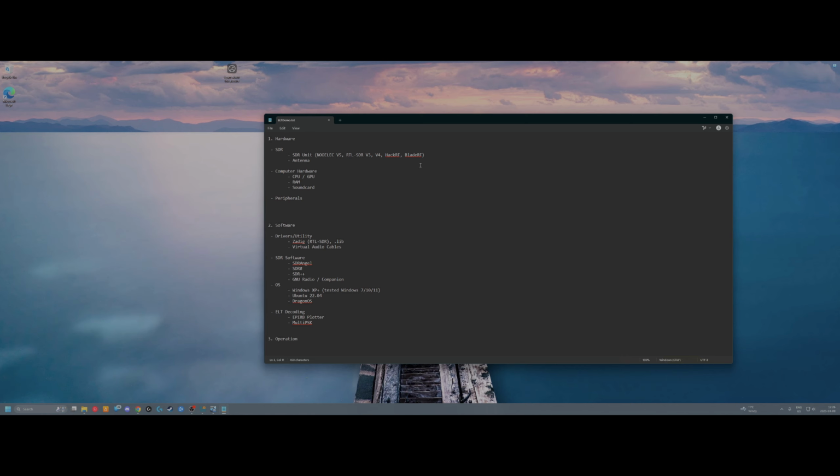I have a version of the Hack RF for things like VOR station emulation. So you can emulate a VOR station and inject that essentially into a nav radio. I also have it for things like VHF comm transmission and reception. Because it's half duplex, it can only do one at a time. The Blade RF is sort of my next iteration once I save up a little bit of change.